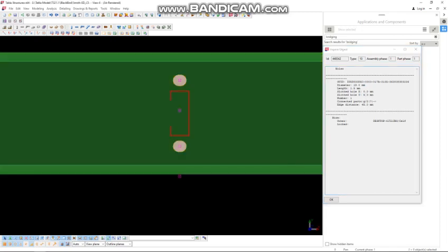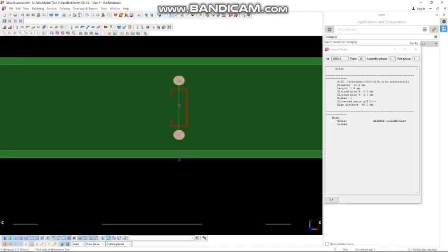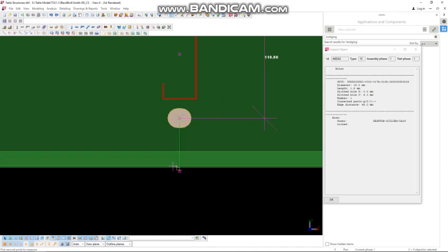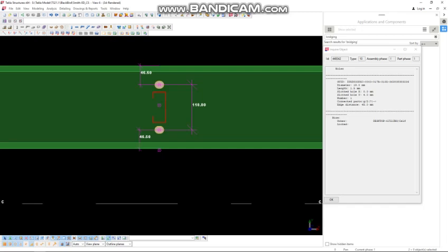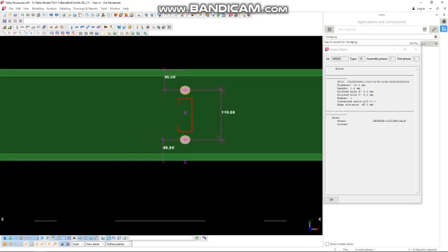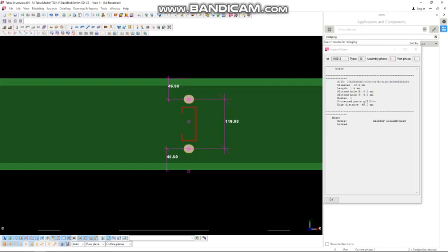So for the location, this is already set as default in Tekla that if the size of the purlin is 200, it would be 110. And also, it is evenly spaced from the center, or evenly spaced with the edge of the purlin. So as you can see, this is a good tool, which is the bridging macro, and I hope that this process can help ease our modeling and prevent us from putting wrong information in our model.